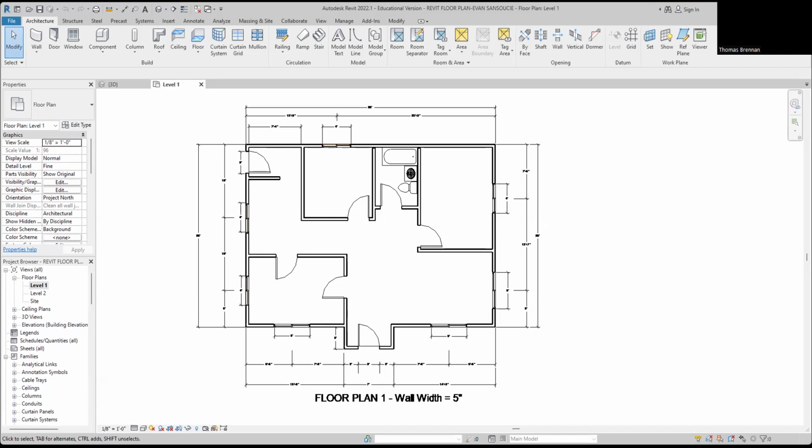And then what you're going to do is, 20 feet, 30 feet, 40 feet, all equals an inch. And then on top of that, you get into all the crazy scales that are in architectural scales. Then you're going to find it a whole lot easier when you get into using metric, because metric's not like 10 to 20 to 30 to 40, all increments of that. Okay, so that's an introduction to working with scales. I want to show you that right there. Let's put these back, and then we're going to get into tonight's stuff.